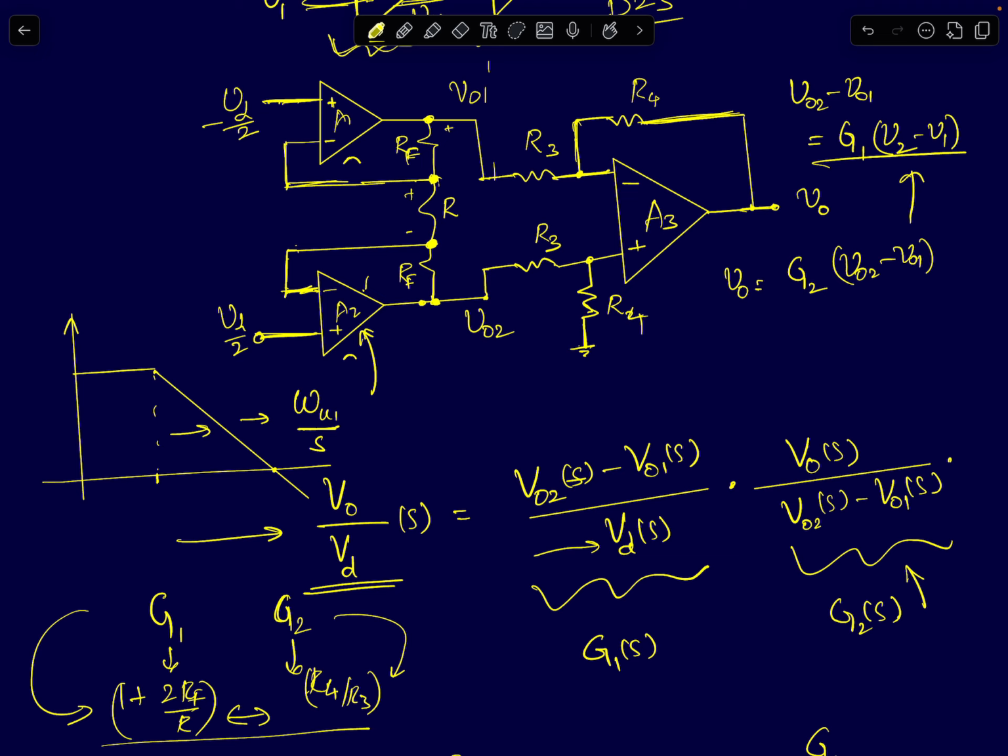Okay, so this is something you have to keep in mind: for the op-amps that we will analyze in this course, we will assume that the frequency dependent gain can be expressed as a DC gain and a single pole. We said this holds very true because of frequency compensation. Normally most op-amps, at least the IC op-amps, employ what we call dominant pole compensation. Usually when you want to realize a high gain, you use a cascade of multiple stages. But multiple stages lead to instabilities. So what do we do? We make one stage where you get very high gain, and we make the pole to be at very low frequencies. So for all practical purposes, or for the mathematical analysis, we can treat the op-amp as a single pole amplifier. And this pole occurs at a very low frequency.